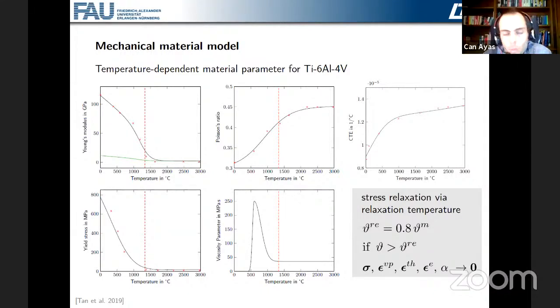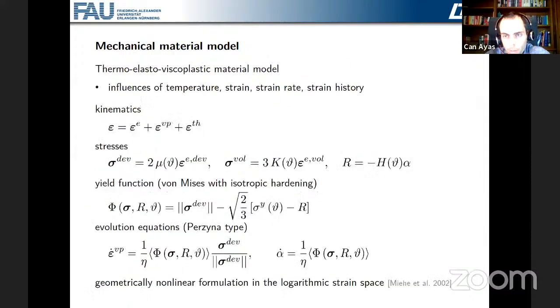First of all, I want to follow up on the geometrical nonlinearity. Well, I was also a bit intrigued about that. One thing, if I understood you correctly, is that when you're doing geometrical linear or nonlinear calculations, I think you're making use of the additive decomposition of the strain. And is it a valid assumption when you're doing the geometrical nonlinear calculations? If you would use a multiplicative decomposition, maybe the discrepancy between the simulations would be a little bit more?